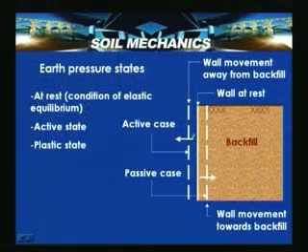Now, consider earth pressure states as told in the previous slide, like the wall moving away from the backfill and the wall moving towards the backfill. Here, the wall movement away from the backfill is shown in this cross section. It is a backfill with a horizontal surface, and the friction between the wall interface and the soil is 0, that indicates smooth, and this is idealized by a Rankine wall, assuming the base roughness is very smooth.